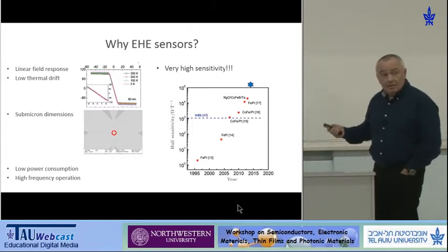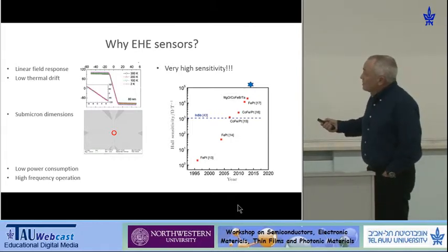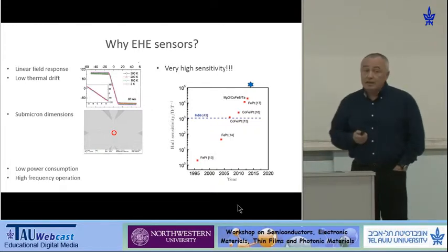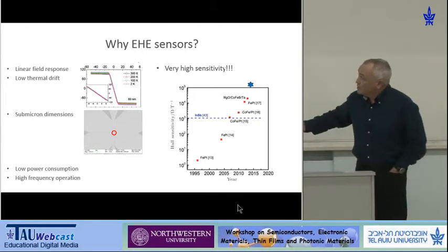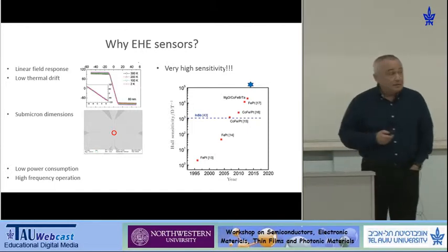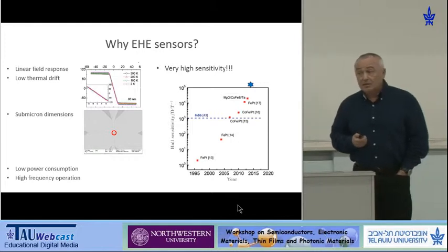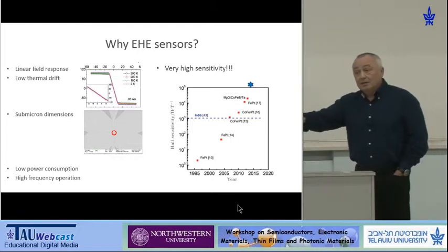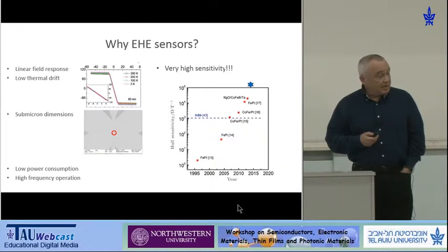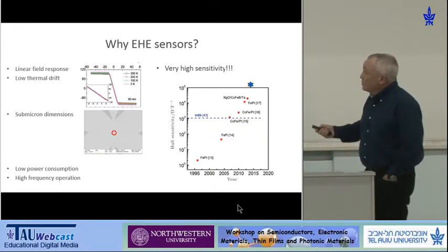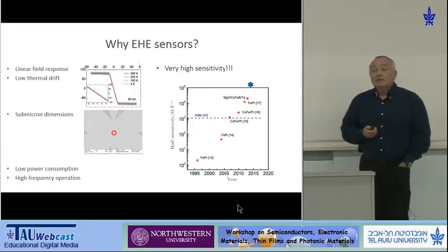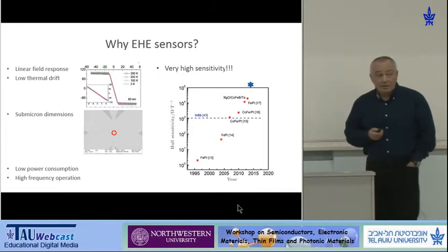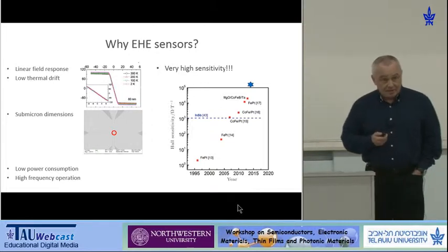the sensitivity. You see, this blue line, this is the highest. Now, the definition of sensitivity here is just the slope, in ohms per Tesla. So what is the change in the measured ohms when we change the applied magnetic field? The highest sensitivity that we know today in the best semiconductors is of the order of 1 kilo-ohm per Tesla.